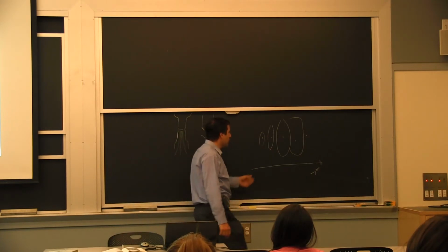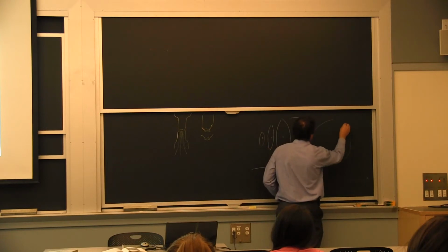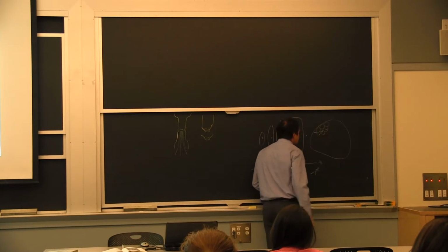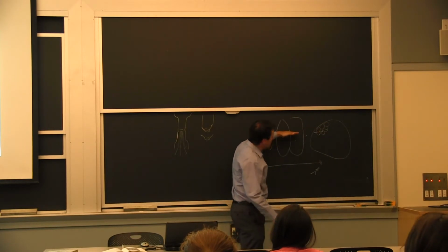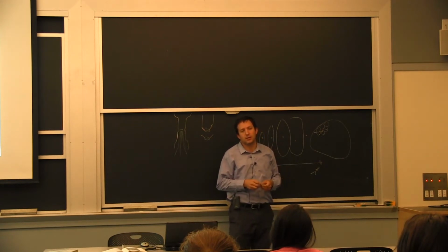But when we go back to a fracture surface, and I can show you a lot of examples of that, you're going to see it this way as little round things. They're not always round. When you see these, we call them dimples. They are essentially a cut view of this where all the microvoids merge together.